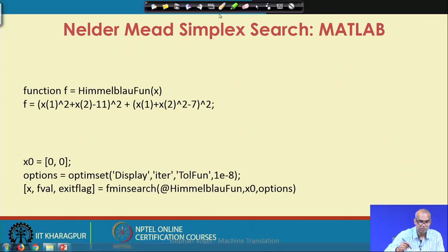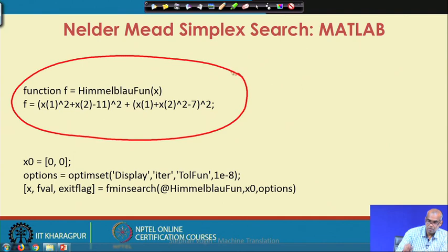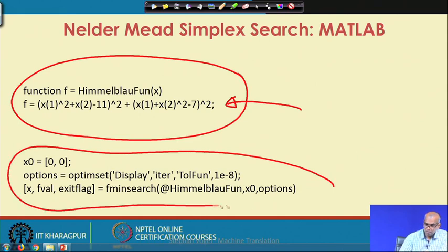To do that, you first write the function, where you write down the expression for the Himmelblau function, and then call the solver fminsearch as shown.